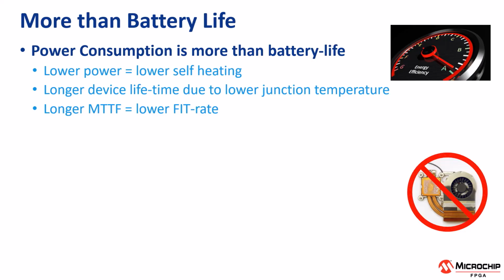Devices that have strong self-heating also stress the board material and affect neighboring devices. Neighboring devices are heated up and will consume more power if they are semiconductors, potentially suffer some secondary aging effects, and may be affected in their accuracy. For example, image sensors have more noise at higher temperatures.